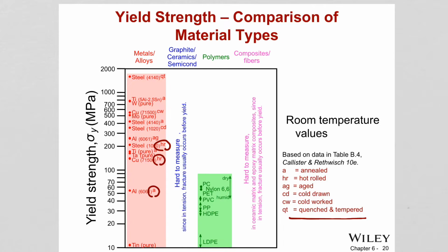The very reason for that is that ceramics are susceptible to sudden fractures, and when we look at the failure chapter we're going to see that. Ceramics usually have pores and cracks inside them, and when we apply tension, this crack can propagate, and then the material can separate into two parts, basically suddenly fail. But under compression the crack doesn't propagate, because you are not pulling the crack apart, right? So that's why these materials are very good under compression.